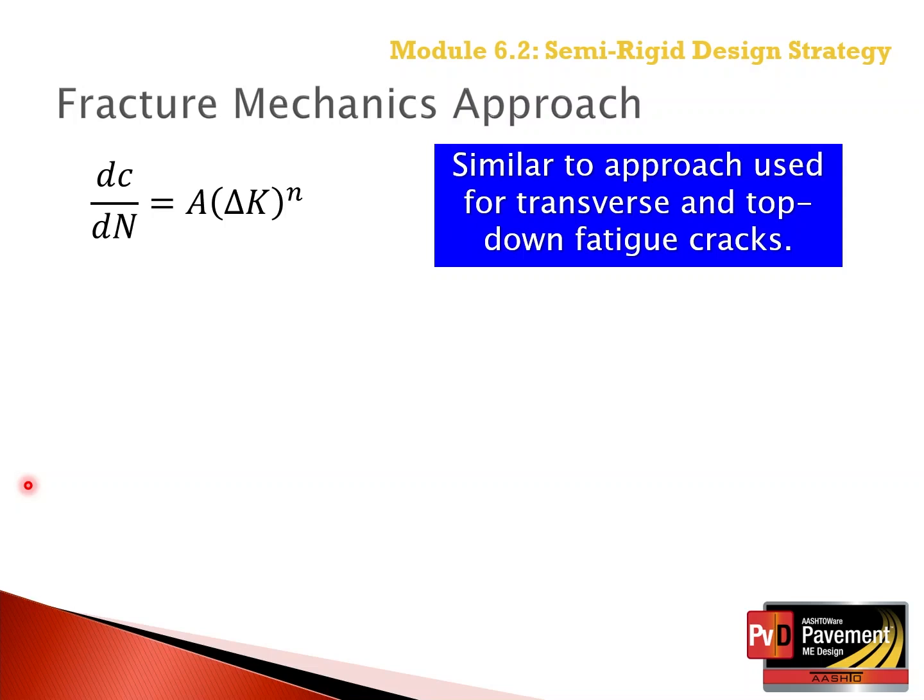The results from these computations of the stress intensity factors were used to develop artificial neural networks that are included in the Pavement ME design software to calculate the stress intensity factors both for transverse cracking as well as fatigue cracks.